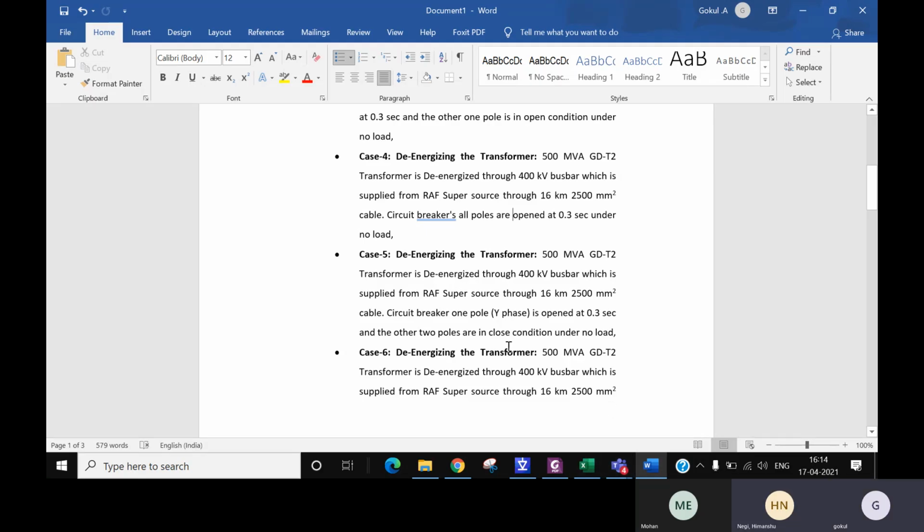In simulation we can do it, but in the real world, if you have a single pole operation, then you can do it, but they don't do it intentionally. I was just trying to estimate the possibilities. Because if you close only a single pole, there will be some oscillations and everything, so they don't do that.